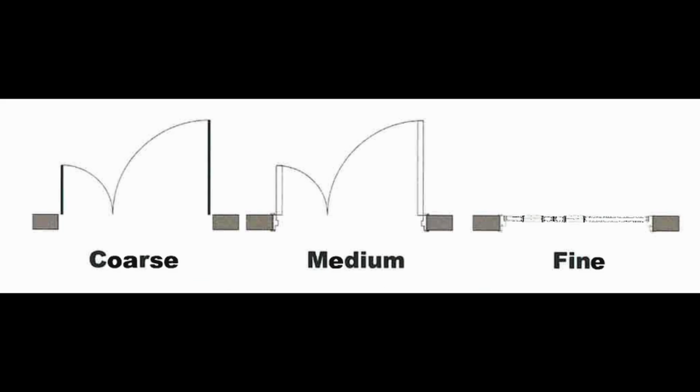Detail level vs component grading. Coarse, medium, and fine detail levels control visibility, not model development. Trying to embed multiple LODs into a single family is inefficient. Best practice is to maintain multiple grades of the same object, simple Grade 1 placeholders, efficient Grade 2 project components, and selective Grade 3 elements reserved only for visualization.